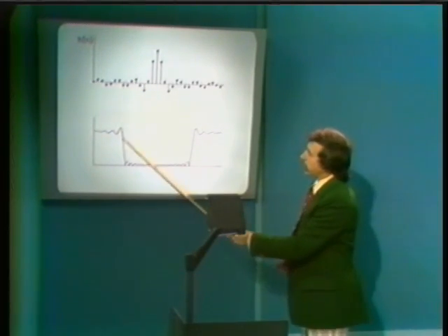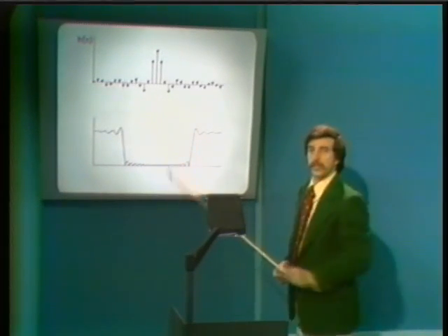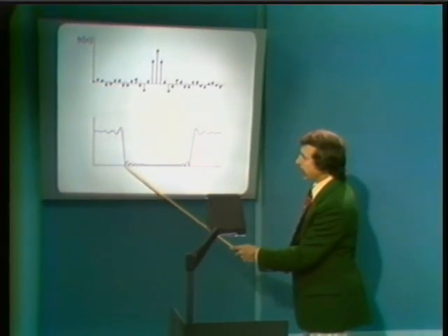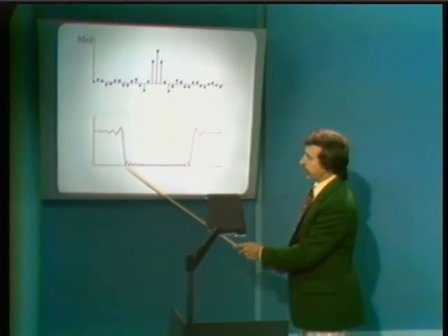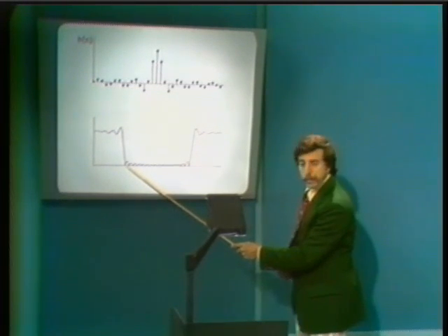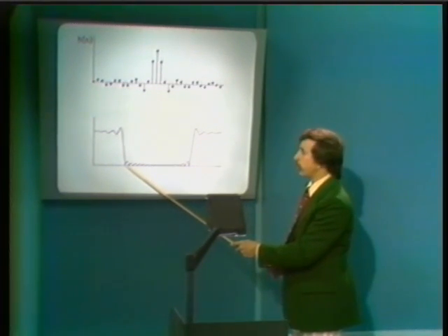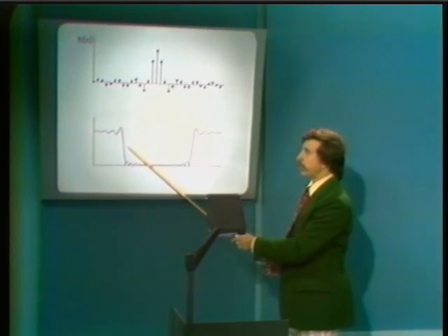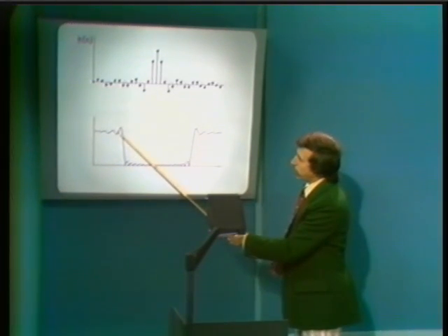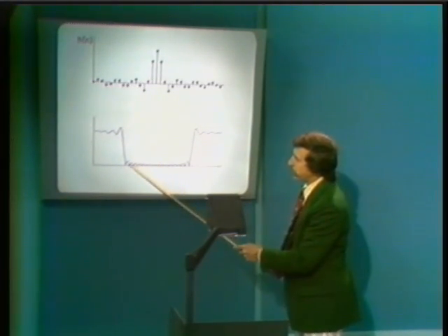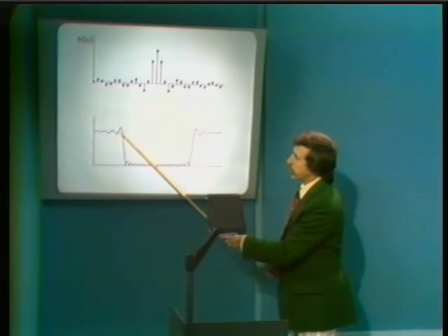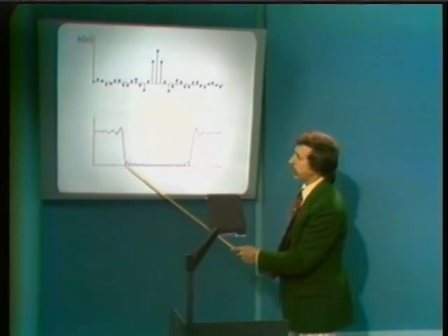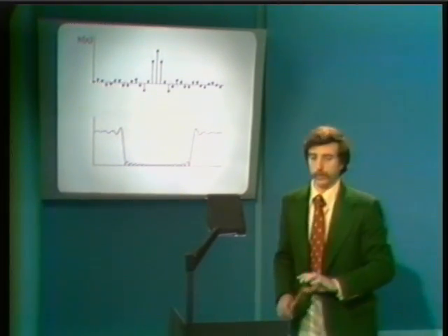How could we widen the transition band? We could imagine beginning with this particular design, taking as one possibility one of the stop band constrained points and allowing it to move into the transition band, so that we have a wider frequency range that we're permitting the transition from pass band to stop band to go over.